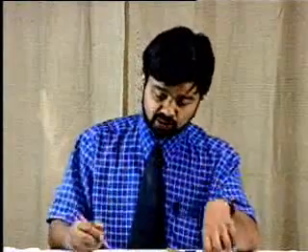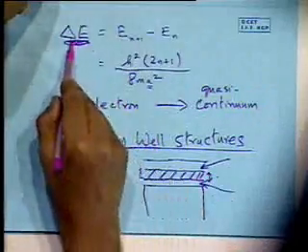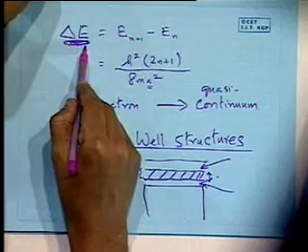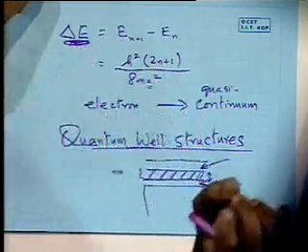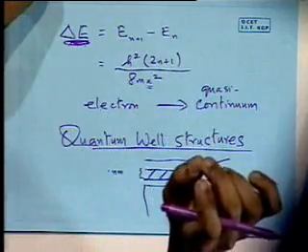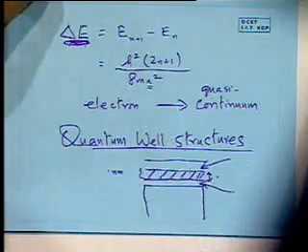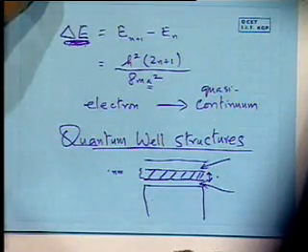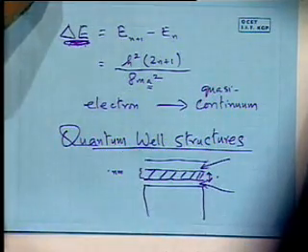very, very sharp levels. And that is made use of in lasers, for example. I want a sharp transition, right? So just by changing the width of this well, I am changing the separation. So I'm able to play with the emitted light from a semiconductor laser by designing what my quantum well thickness should be. Okay? That's exciting. I can engineer what light I will get out of the same material, of the same composition, except all I'm doing is playing with the thickness dimension. So it's a very practical application of what we are looking at right now.